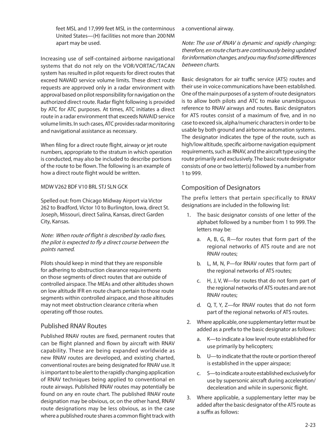Increasing use of self-contained airborne navigational systems that do not rely on the VOR/VORTAC/TACAN system has resulted in pilot requests for direct routes that exceed NAVAID service volume limits. These direct route requests are approved only in a radar environment with approval based on pilot responsibility for navigation on the authorized direct route.